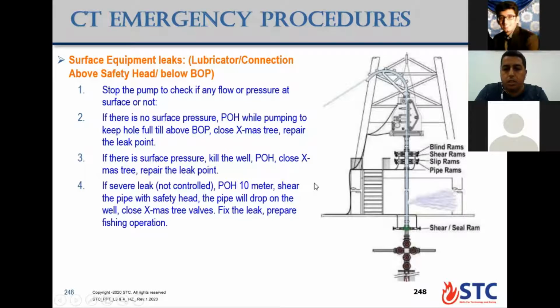Ahmed, how will we kill the well? Will we kill the well through coiled tubing or will we do bullheading? I guess we will do bullheading. You can bullhead from the Christmas tree to pump some kill fluid inside the well. Bullheading is the option, right?